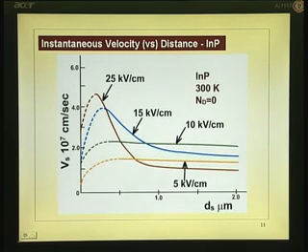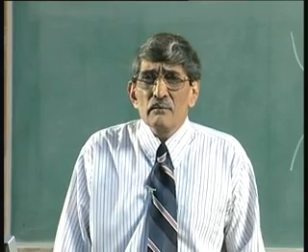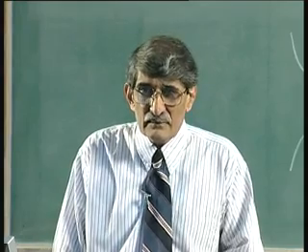Now, one thing I was avoiding all the time is discussing the transient effect in silicon. Because of the difference in the momentum, as the velocity increases, energy increases and the momentum also changes, so the electrons get transferred from the lower valley to the upper valley in the case of gallium arsenide and indium phosphide. As a result you get this velocity overshoot effect, because of the time difference between the relaxation time of energy and momentum, since the momentum difference is so large from one valley to the other. So, silicon people started asking, don't you see a similar effect in silicon? Yes, you will see that.